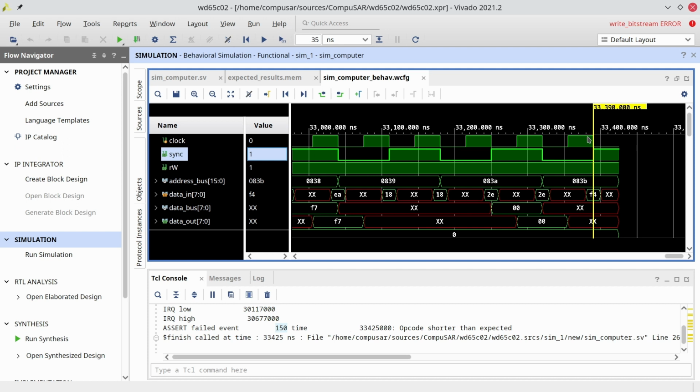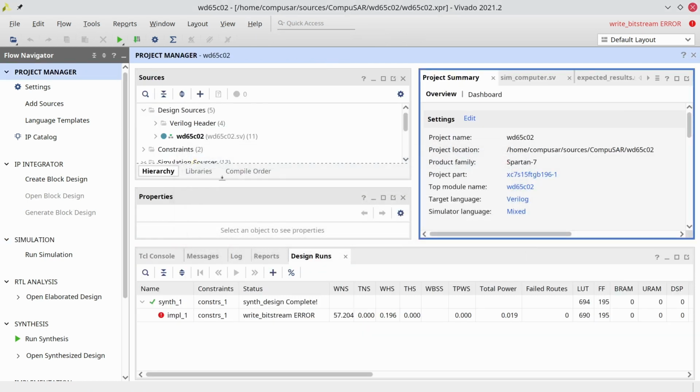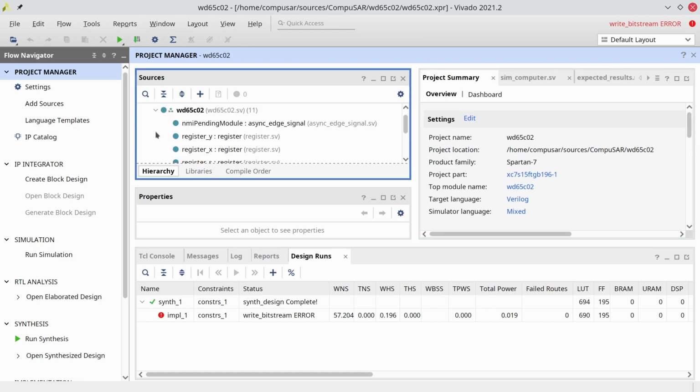It means that now we can automatically test whether we've implemented correctly the opcode. That is a huge thing. It means that as we continue to implement opcodes in the CPU, all we have to do in order to make sure we haven't broken the rotate left opcode is run the simulation. It will automatically make sure everything's in order. With that out of the way, we can finally start implementing the actual opcode.